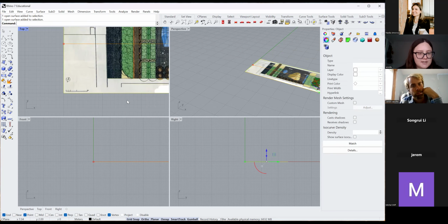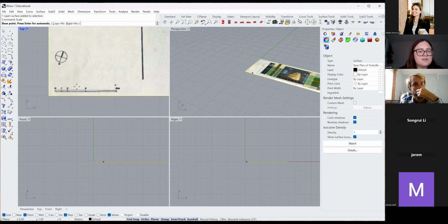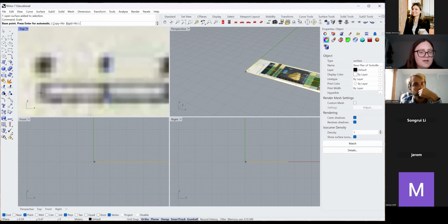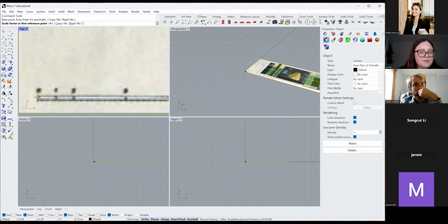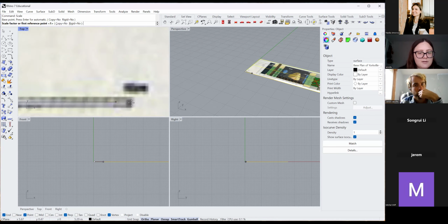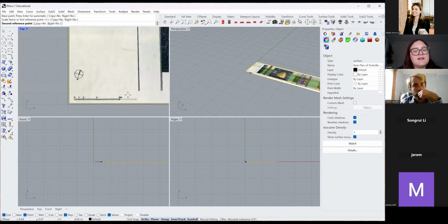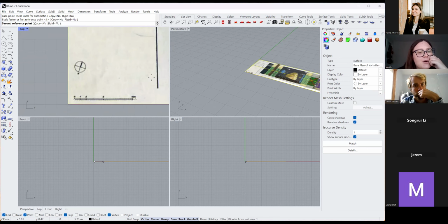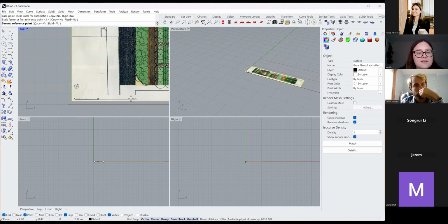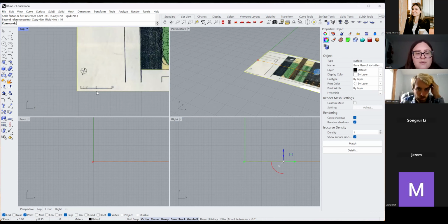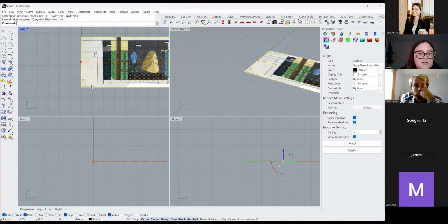and I want to make sure that everything is to scale. So what I'm going to do, I'm going to click it and type in scale. And I'm going to go into this scale bar and approximately get it to where the actual line would be. Okay, and so it's asking for a second reference point. And so I want to tell Rhino that this line that I just created is supposed to be 10 meters. So then you click 10. And now this should be 10 meters.